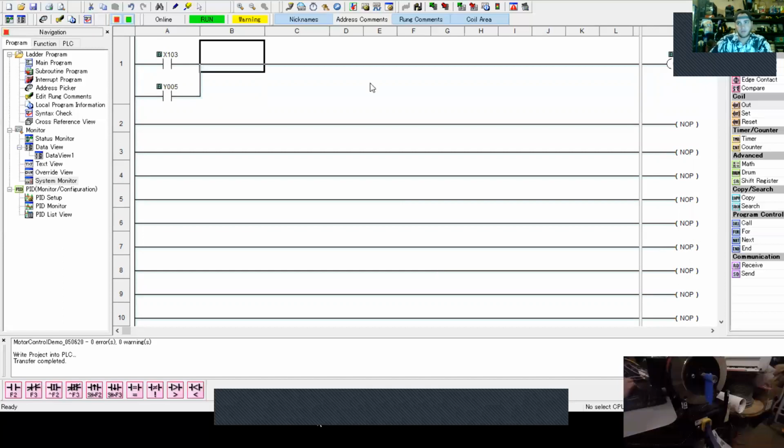And then we need to make our interrupt to stop that latch. We need to pick something that makes sense. Now, if you'll remember back to what we talked about last time, we need to have an up and down input for the counter. So that's 2 buttons. We need to have our start button, which is 103, and we need to have an interrupt button. So what I'm going to do is use the E-stop button as our interrupt. And we know that that's X104.